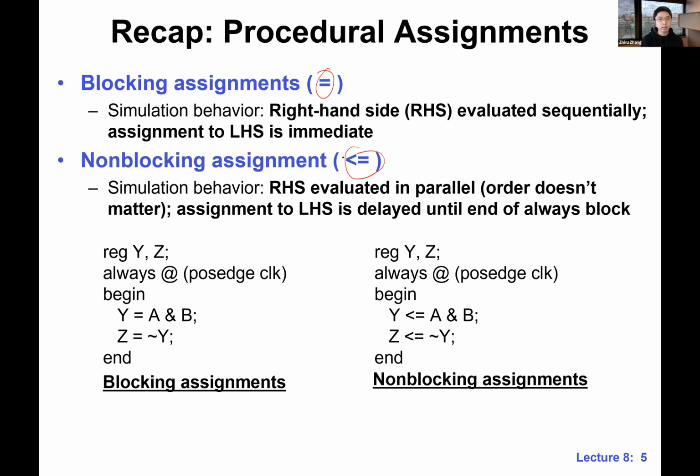It's really the algorithm that the CAD tool, like ModelSim, uses to generate a waveform. ModelSim will assume that for blocking assignment, the assignment is immediate, and for non-blocking assignment, the assignment is delayed, so it happens at the end of the always block.